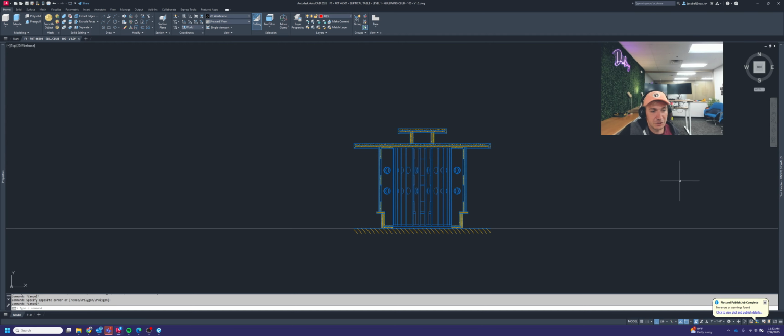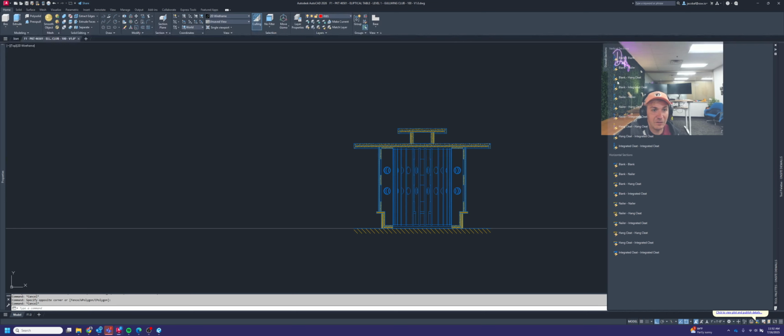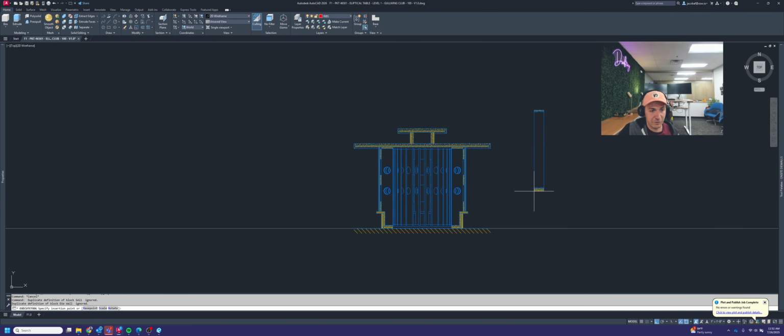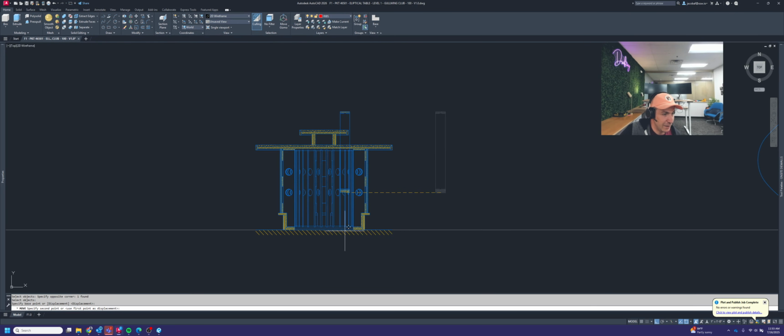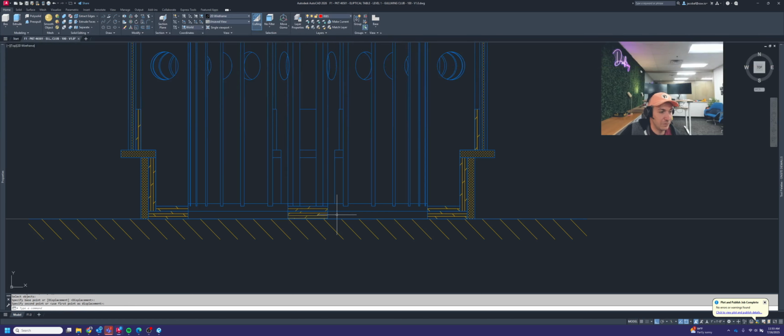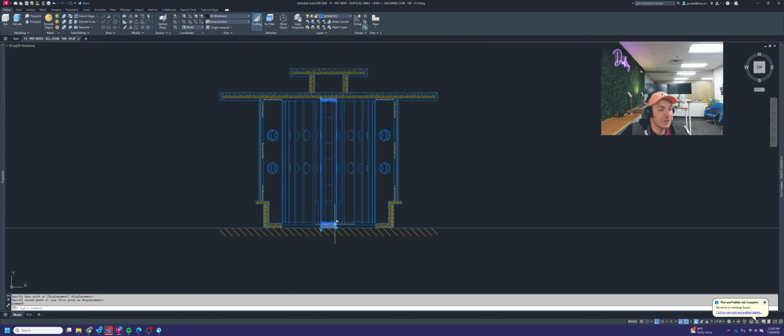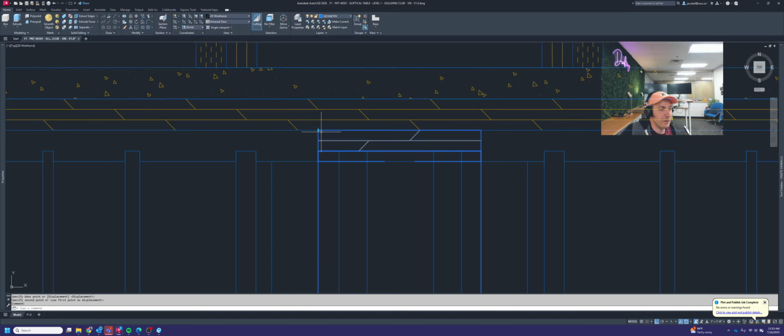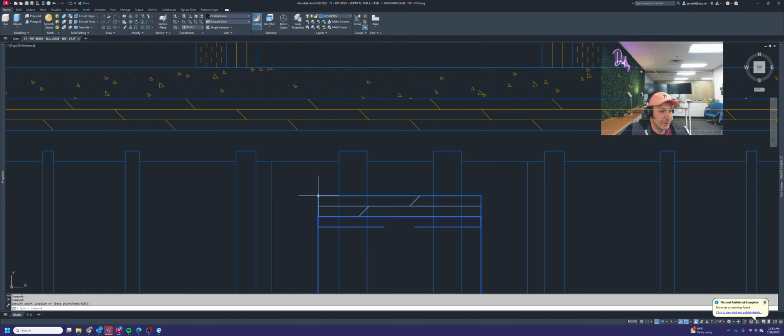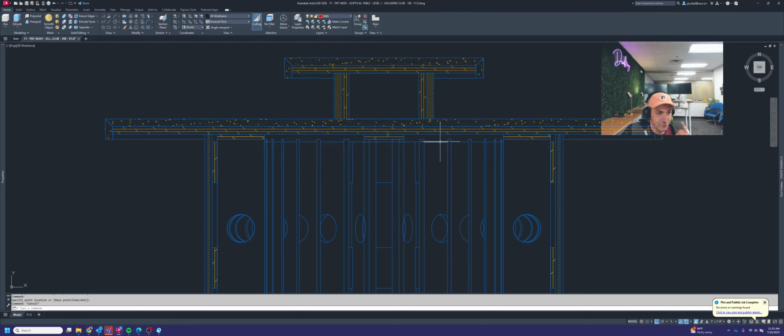To show that, you can grab the vertical blank die wall section that's here, and we can drop that into our vertical section through the middle of our table. Then we first make sure this is at the right height, and then we have to trim everything to the outside of that.